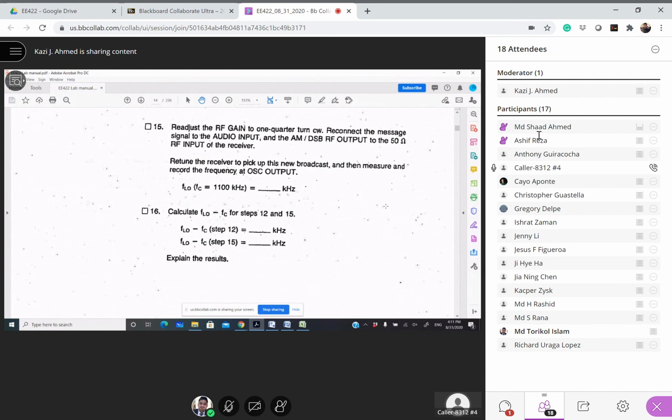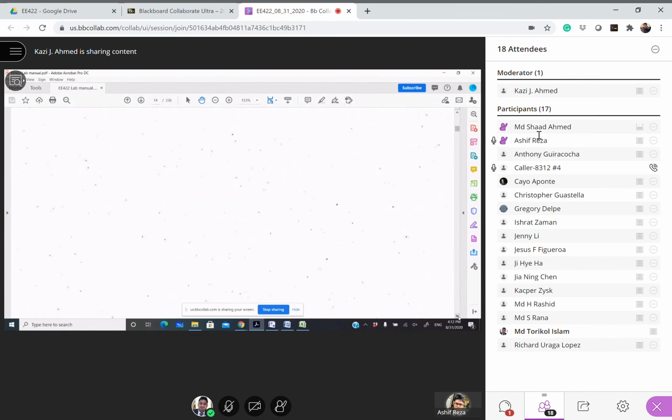Some of them do. Also, when you change the carrier level and the gain, try to use your pre-lab Simulink module: put an extra gain at the end of the modulation and increase the value beyond 1 and less than 1 to see what happens. Also change the amplitude of the carrier, only the carrier, and see what happens. You can put the figures or waveforms that you see onto your lab report.